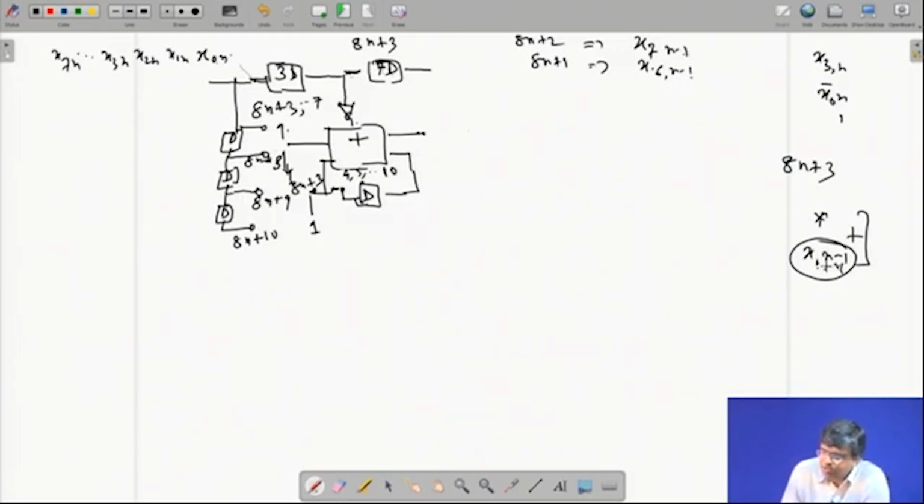then you will get this x1n minus 1 here. You can also verify another way. If I delayed by not 7 but 8 cycles, a very interesting thing will happen. What will come here at 8n plus 3? That thing which was here 8 cycles ago. Now currently I have got x0n and the data size is 8 bit, so 8 cycles ago x0n minus 1 would come. All the 8 bits of x0n, x1n, x3, they will come later. Suppose I delay it by 8D, not 7D.